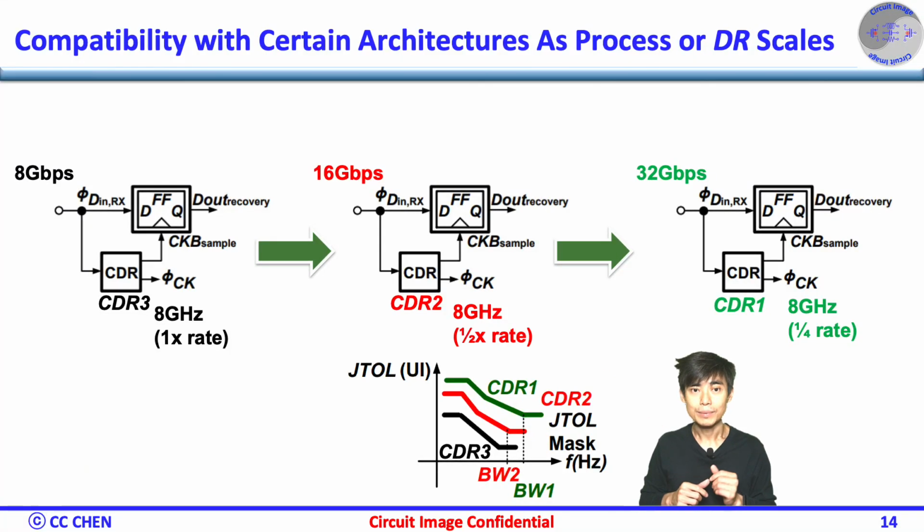As we discussed in our previous block, when the data rate continues to rise, the full-rate CDR becomes more difficult to implement due to the limitation of current technology in generating and handling very high-frequency clocks. Fortunately, the half-rate CDR offers a scalable solution by halving the clock rate, which can accommodate future increases in data rate without requiring fast clocking technology.